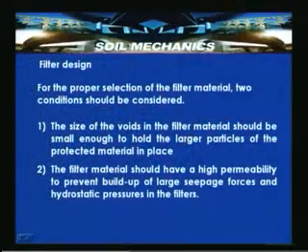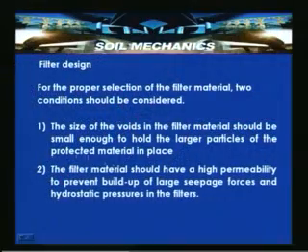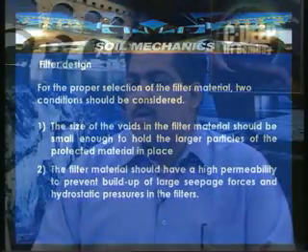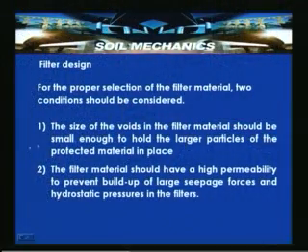The first criterion is that the size of the voids in the filter material should be small enough to hold the large particles of the protected material in place. If this material gets washed out of the filter material, then the stability of the structure is endangered. So, that is criterion number 1.